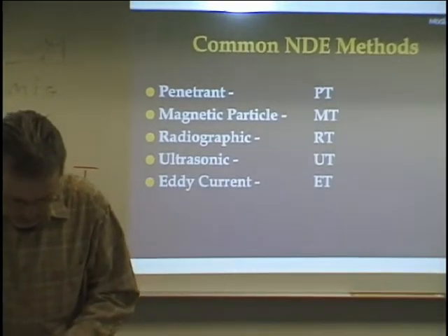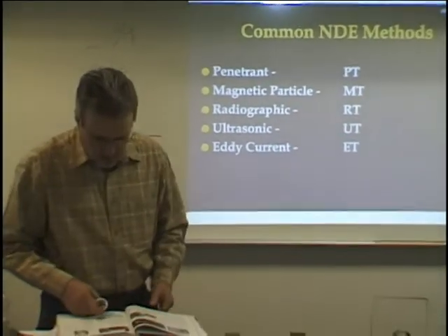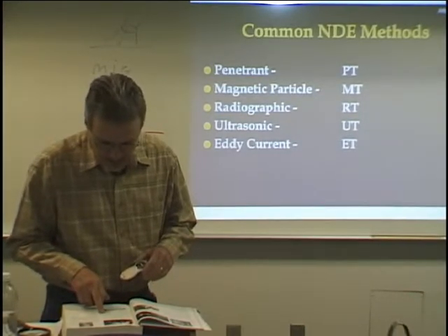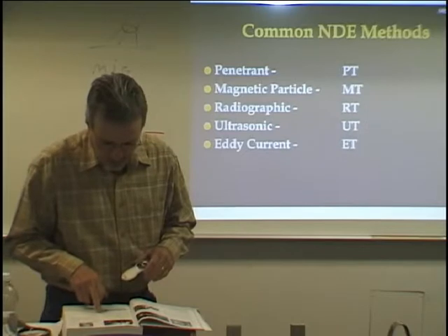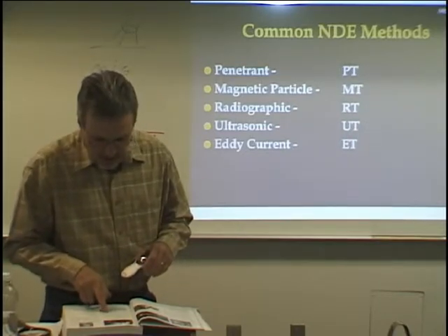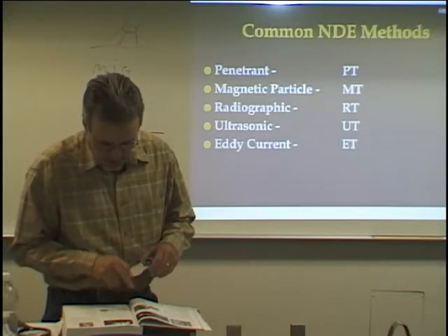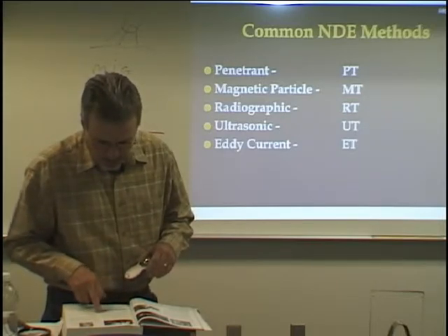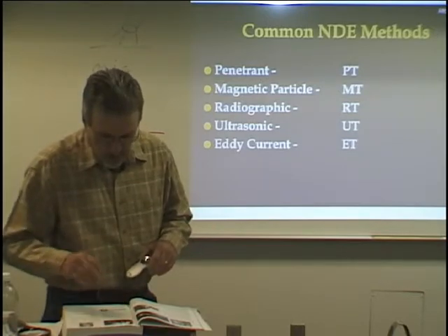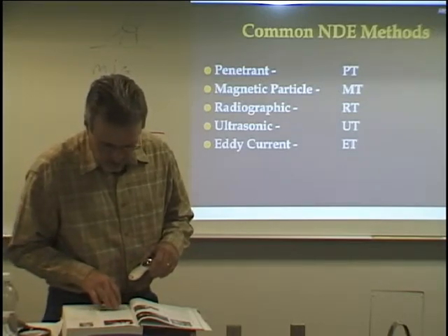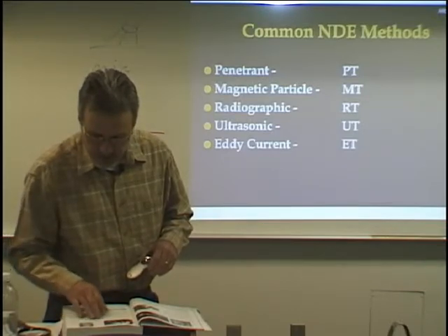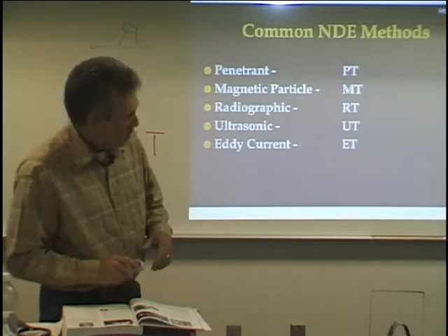Okay. Let's see. Continuing. Highlight where it says welders must also be able to cut metals with the oxyacetylene cutting torch and with the various cutting procedures involving the plasma arc cutting machine. This is a bullet. Flame cutting is often the only practical method for cutting parts or repairing steel plate and pipe. Plasma arc cutting is used to cut all types of metals. Proper use of an electric or pneumatic grinder will save many hours in the welding process.